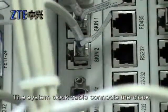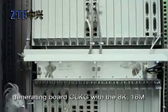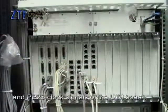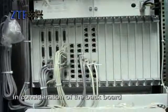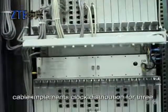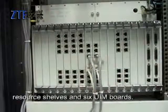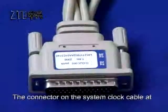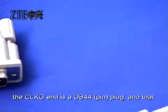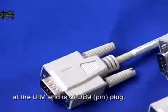The system clock cable connects the clock generating board CLKG with the 8K, 16M and PP2S clock signals of the UIM board. In consideration of the backboard connector space and cabling, each system clock cable implements clock distribution for 3 resource shelves and 6 UIM boards. The connector on the system clock cable at the CLKG end is a DB44 pin plug, and at the UIM end it is a DB9 pin plug.